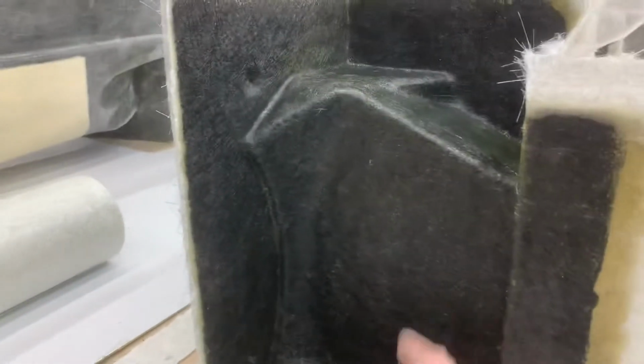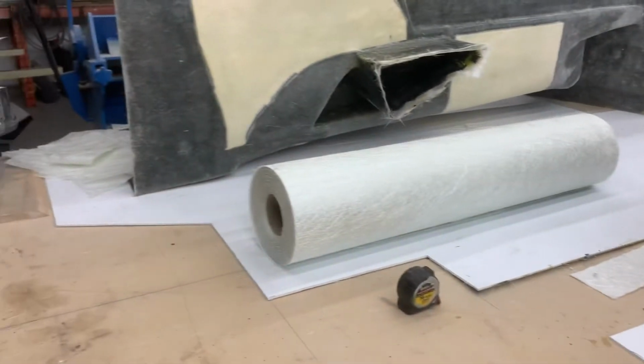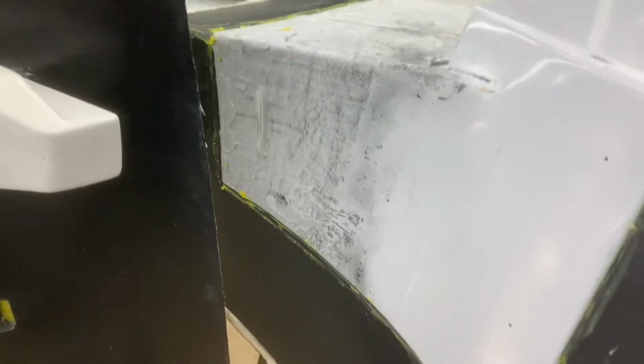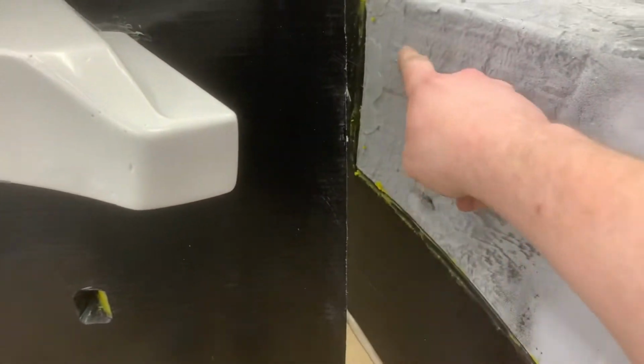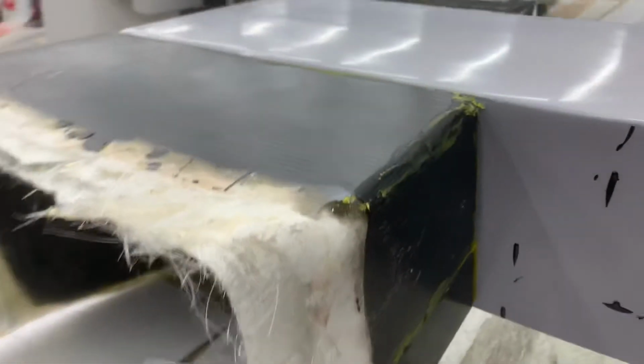Molds, carrying on. We're on to the 3rd section of the side sill mold on this one, and then the 2nd section on that one. There's 5 sections underneath, so it's still pretty boring going on. The diffuser tunnel mold now is just curing, just waiting to go off. So you can see the huge black flanges on there, which realistically the only part we need is the part that's behind here. But we need these flanges just to make the vacuum bagging considerably easier.